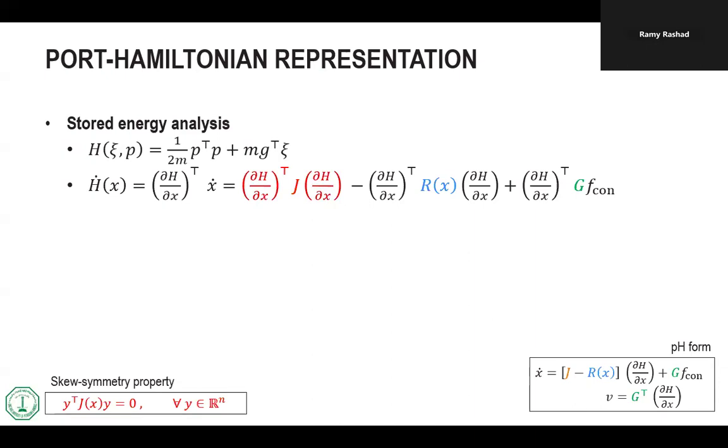It's equal to 0, just because of the skew-symmetric property. It's always the case, even if this J was a function of X. Which means that if you have a nonlinear system that's very nasty, and you spend a few minutes or maybe a few hours trying to cancel this term with that term, and so on, if you really deal with something complicated, in the end, it's just inside of the J. If you write it in the Port-Hamiltonian framework, this is a technical advantage. When you're doing analysis, everything in the J just disappears.